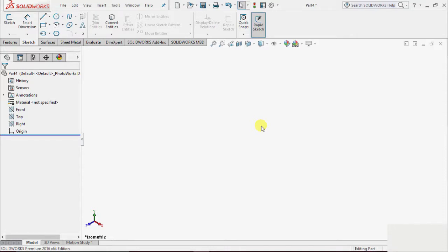In this tutorial, we will continue our sketch modeling and we will learn about the next type of sketches, that is rectangle. As we know, rectangles are four-sided structured profiles that are closed. So we can find this rectangle command below this line command. If I click on this arrow, we will find some types of rectangles such as corner rectangle, center rectangle, 3-point corner, 3-point center and parallelogram.